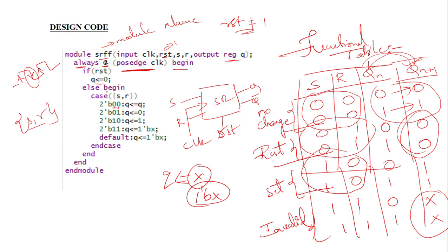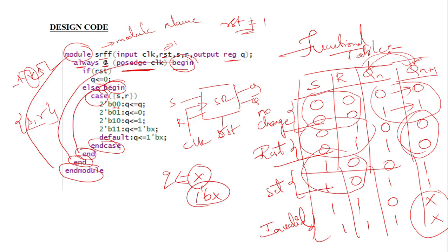Whatever case we are using, it ends with the endcase keyword. There is an else begin here, so we have to end that too. Whatever always begin we are using, we have to end with the end keyword. A module ends with endmodule. Whatever the beginning, there is an ending statement: begin ends with end, and case ends with endcase. We have to make the block inside this begin and end, otherwise it will terminate and give some error.